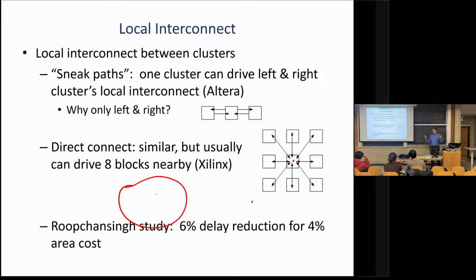And so they use repairability, right? It's connected by sort of a bus-based FPGA-style interconnect, like a spatial interconnect. And you can't yield that thing. Like you can't yield 900,000 perfect processors. So they use similar techniques to basically shift around broken things. They've never revealed exactly how they do it. It's not entire rows. They can go around individual broken processors, which is intriguing. So I don't know exactly how they do it.